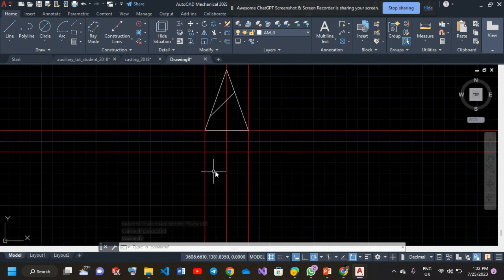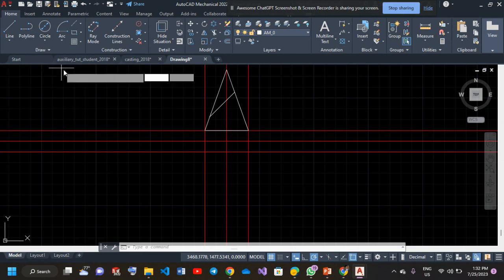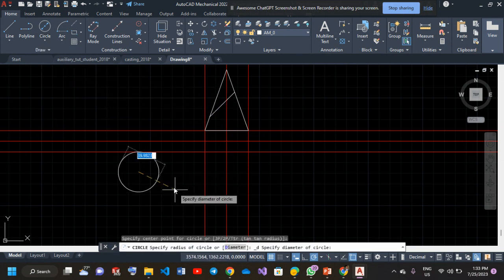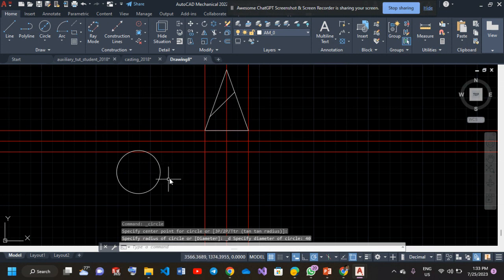I need to get the top view projection, which is going to look like a circle. And the circle is going to take the shape of the base. So the circle is going to be a center diameter circle with what? Distance 40 or diameter 40. So I'm going to move this circle to flash with this one.